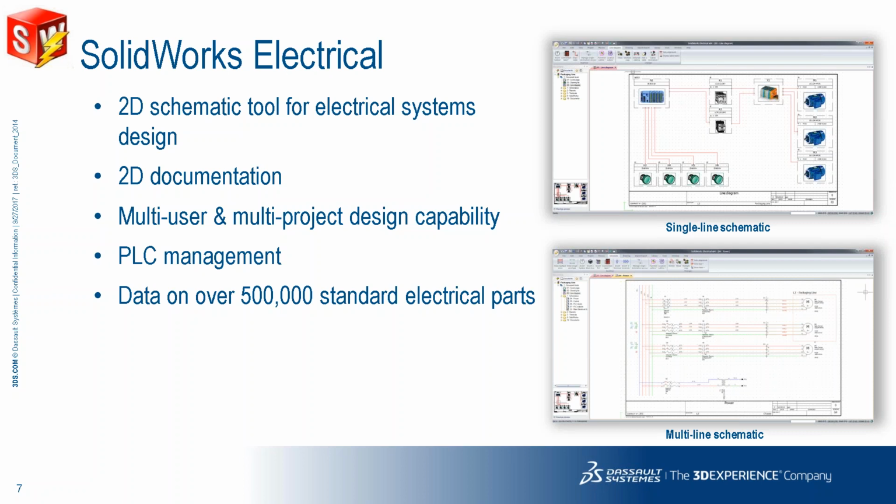And it also has the capability to have 2D documentation, which is all the drawings, bill of material, wire list, terminal strips list. So you can have a massive number of documents out of your projects when you are using SolidWorks Electrical. And it's by default a multi-user environment if you are thinking about SolidWorks Electrical Professional. But there is a smaller package, which is SolidWorks Electrical Standard, which is single user by default. So in this case, if you are thinking to develop your component alone and you're not engaged with other users, the best fit for you is SolidWorks Electrical Standard,